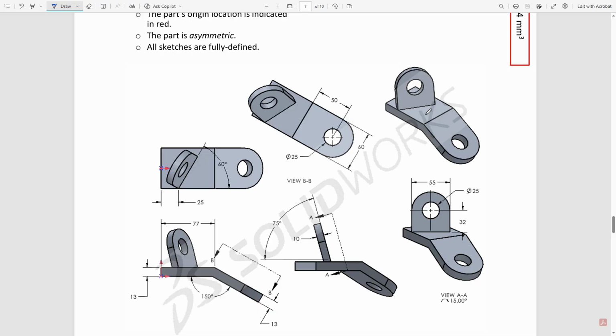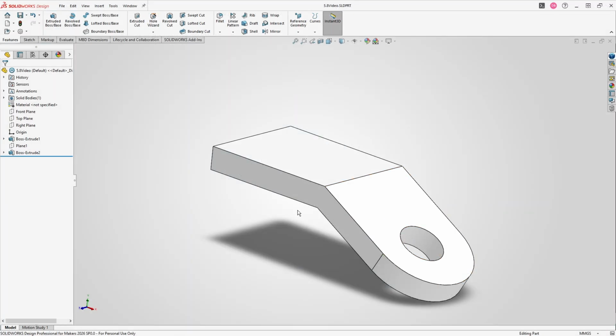All right, so I'm actually going to create this center line also so that it's the correct length, which is 55. So that's going to be the length of that center line. And the center line is going to have an angle of 60 degrees, and it's going to be starting at 25 millimeters from this edge. Let's try to put all of that into play here.